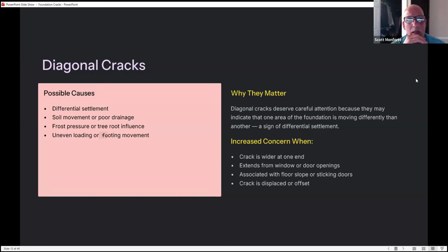So where you get in trouble is if you say it's not a big deal, don't worry about it. I always make note of it, and in my narrative, I'll say to have somebody who specializes in analysis and repair come out and take a look, because those cracks can be sealed several different ways. There are several companies, whether it's epoxy injection or the way Larry Janeski does it, with this membrane he puts over it and then puts a hole and it drains down in there. But the thing where you get in trouble is when they start to leak and water gets in, especially if they finish the basement. If you make note of it, don't just blow it off. Chances are it's not a big deal. The house isn't going to fall down. It's not displaced. It's just a vertical crack.